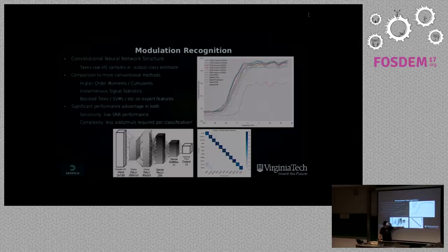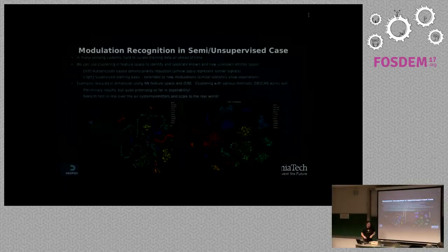So these correspond to one per modulation class. You typically use a one-hot encoding for a classifier. If you go back one layer, you have this feature map of activations between each layer. And generally, this is reducing in size as you go through the network to become a more and more concise representation of the information. So if we go back one layer and we just take these activations here, we now have basically a compressed representation of the signals from the input in this feature map space.